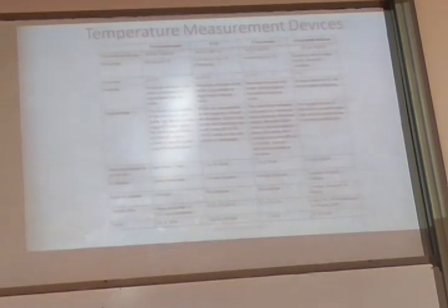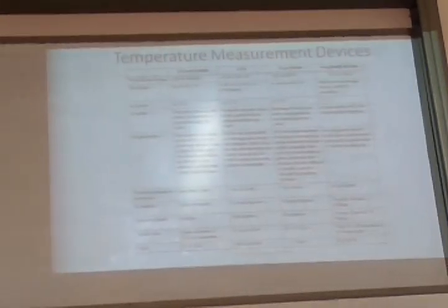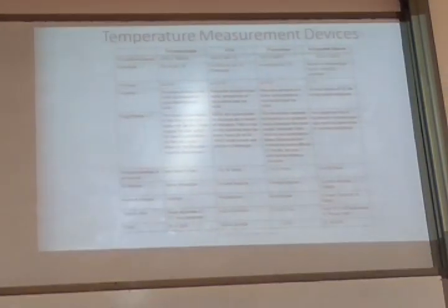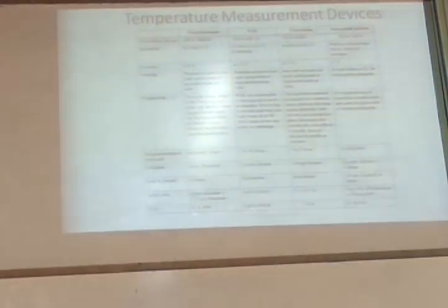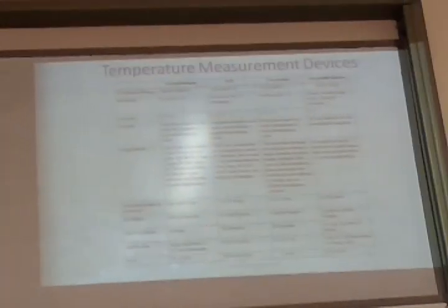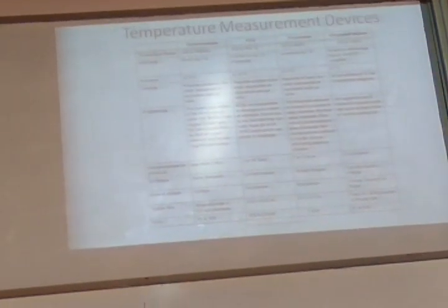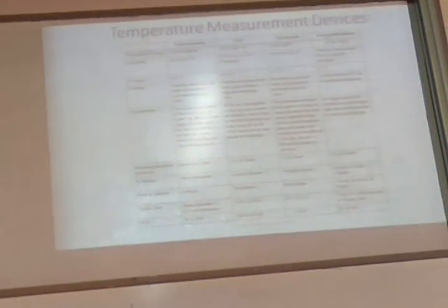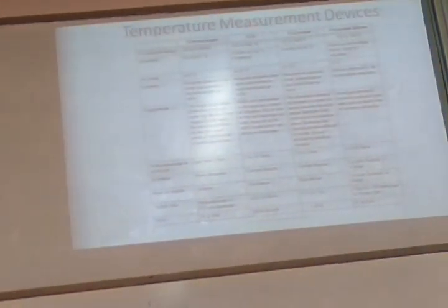In many machines, we want to know whether the temperature is going much beyond the room temperature. It's a small indication. We are not interested in the exact temperature value. A crude value, whether it exceeds the threshold limit, is very useful because at a cheaper rate, you can directly integrate it into the analog to digital converter. ADC systems you can directly connect. Whereas thermocouple, if you have to connect it to a computer, you need a much more complicated data acquisition system. Connecting this integrated silicon is much easier. Signal processing is very less.